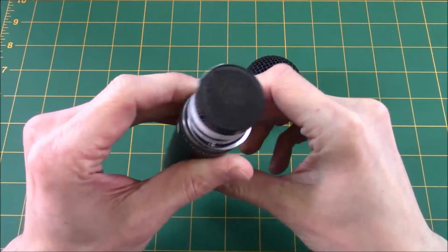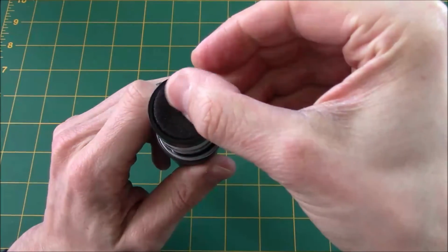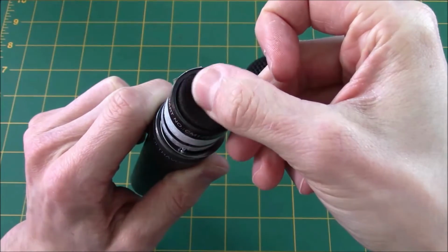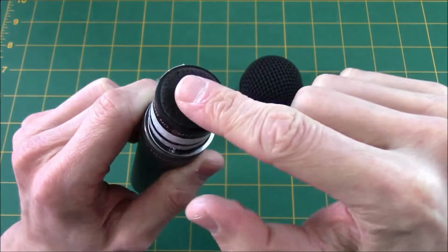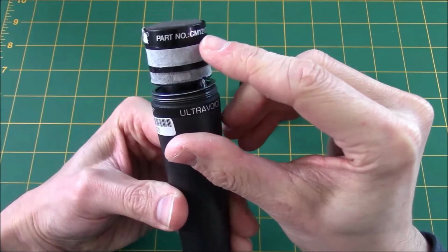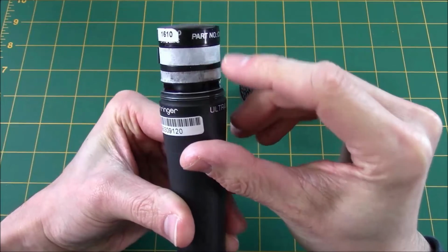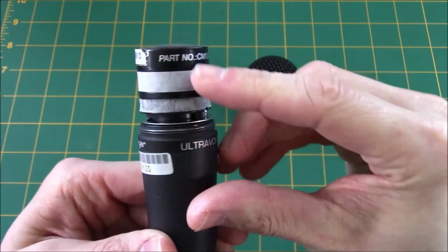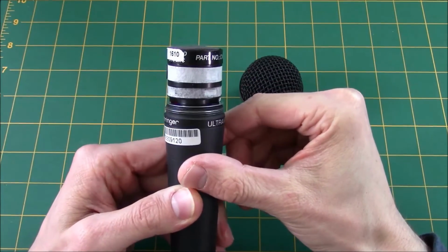Here's our microphone. Behind this 1-inch opening is a diaphragm. The foam is held down to prevent me from pulling it off without damaging the diaphragm. There's a metal backing behind the foam also to prevent damage. You can feel it as you depress on this. The microphone is lined with these additional sides that have partial felt covering and an additional chamber on the back side. All of these passages allow interference so that the cardioid pattern can be amplified.